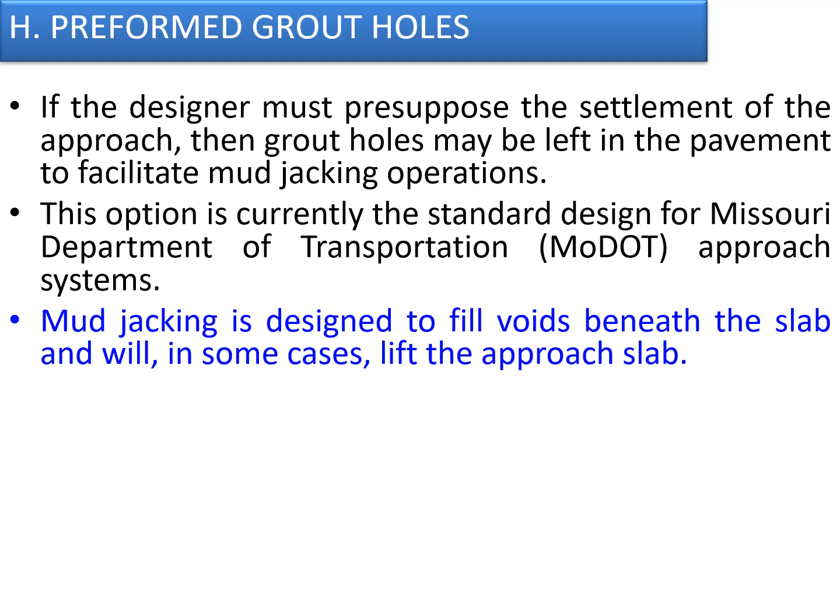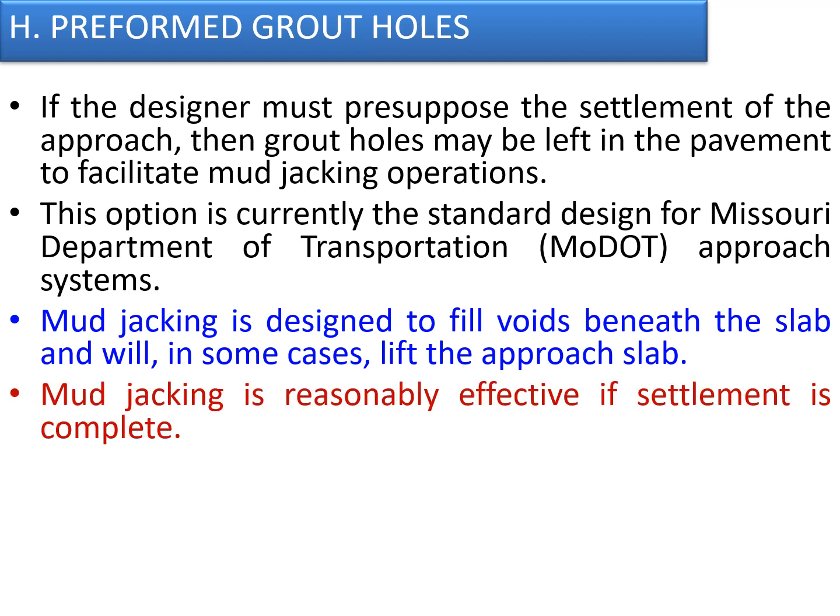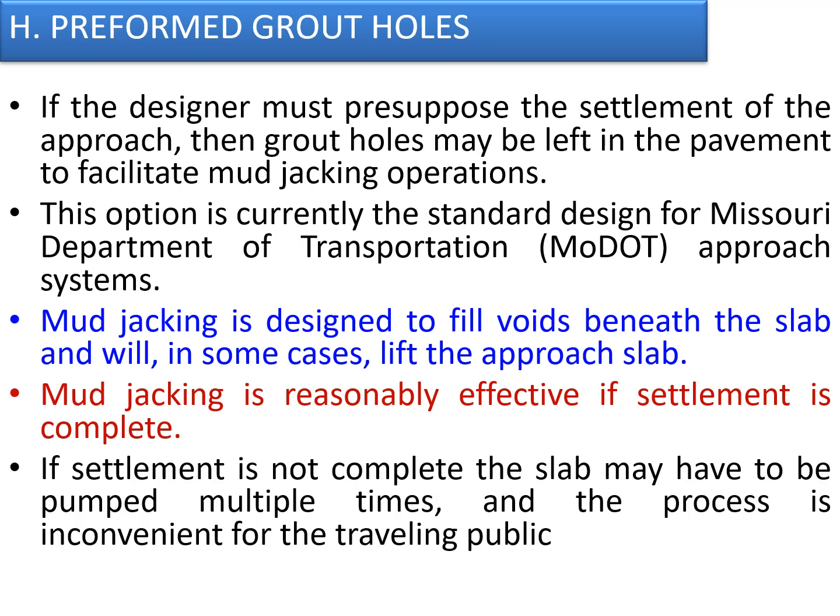And mud jacking is reasonably effective if the settlement is complete, and if the settlement happens to be repetitive in nature, then the mud jacking process needs to be implemented multiple times, which is sometimes time consuming and is an inconvenience created for the traffic also who are plying on that road.